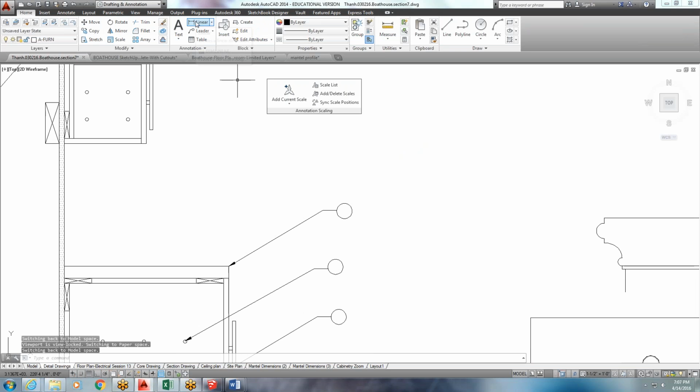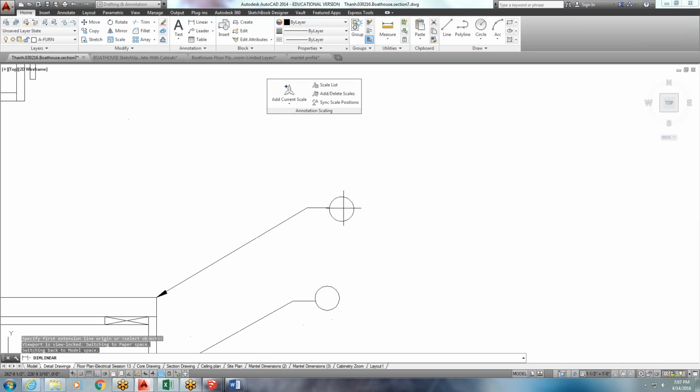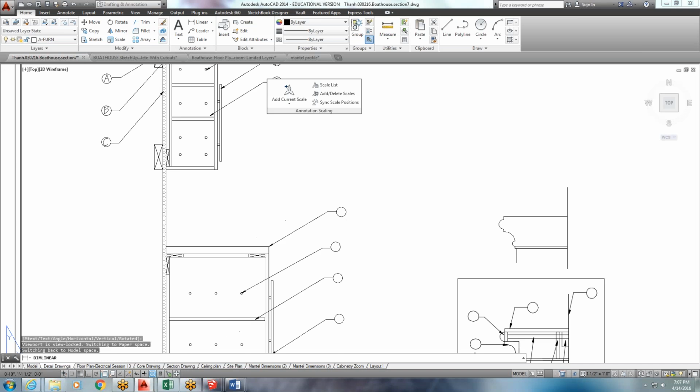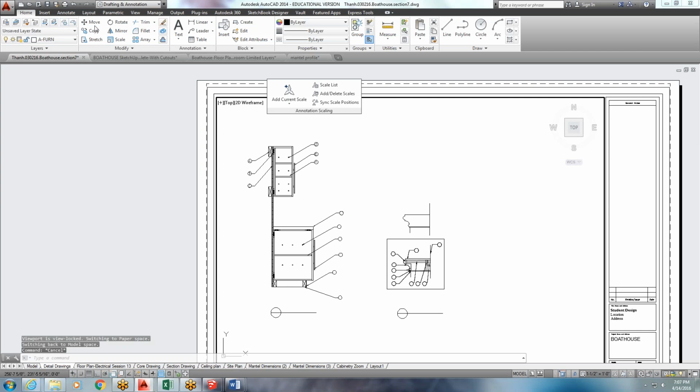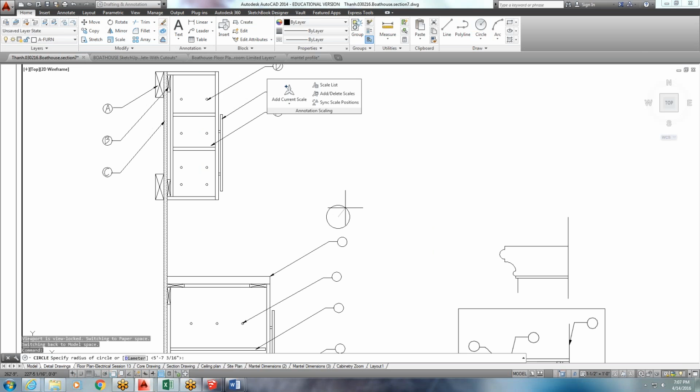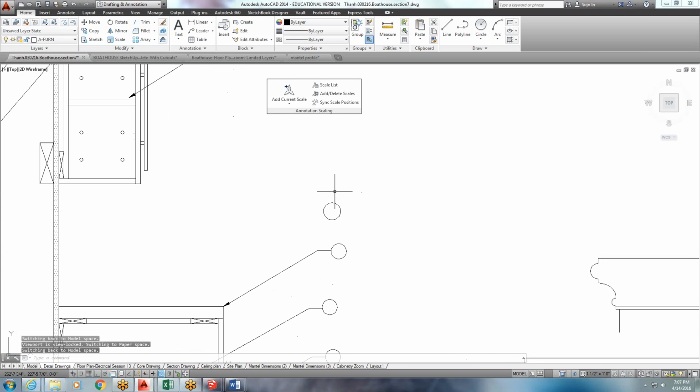So my circle, for those of you who really want to know, I'll turn on my point, is 1¼ inch. But if I go to draw that circle in paper space within, or model space in paper space, let's see, my circle guy, put him up here. Let's see what really happens when I do 1.25, enter. Okay, so it is accurate. It's 1 and 0.25 for the circle.